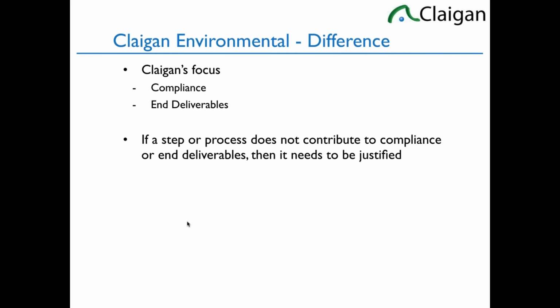And as you go forward, more and more of the restricted materials compliance will focus on the custom parts and materials versus the off-the-shelf. You're going to realize more and more it's your design that has to be compliant, not the part you buy from DigiKey or Newark. The compliance burden and material types are less and less circuit board and standard electronic components and moving to other materials.